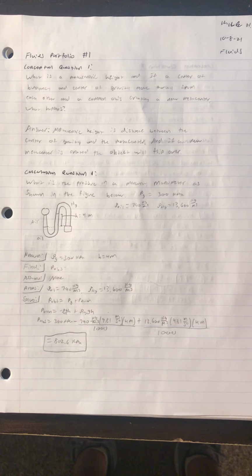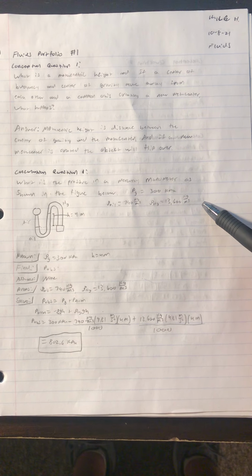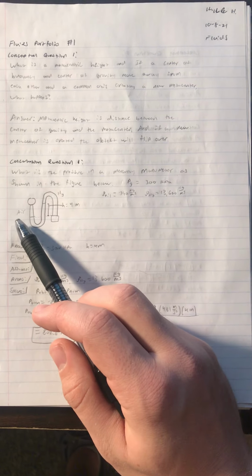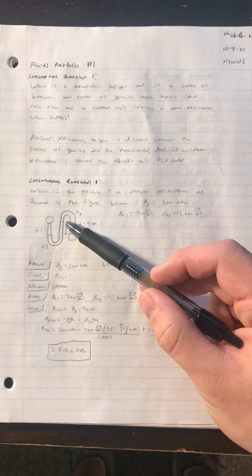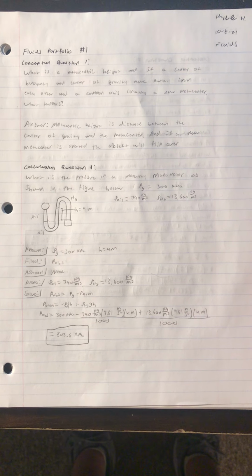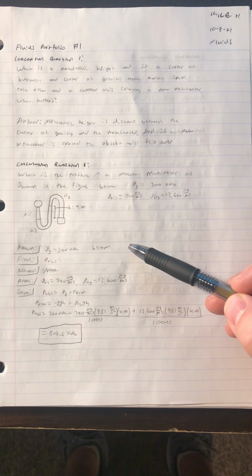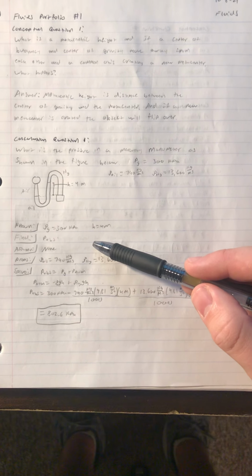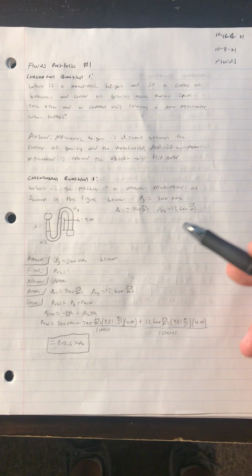The first calculation question is, what is the pressure in a mercury manometer as shown in the figure below? And this is not just purely a mercury manometer. As we can see, it has air, oil, and mercury in it. So there's two loops, and there's two different fluids on the loop, so we have to account for the differences with that. But first, we have to do our knowns, which is we know there's a gauge pressure of 300 kPa, and we have to find our absolute pressure. We don't really have any assumptions, as this is a manometer, so there's not much to assume, as it's usually pretty straightforward.